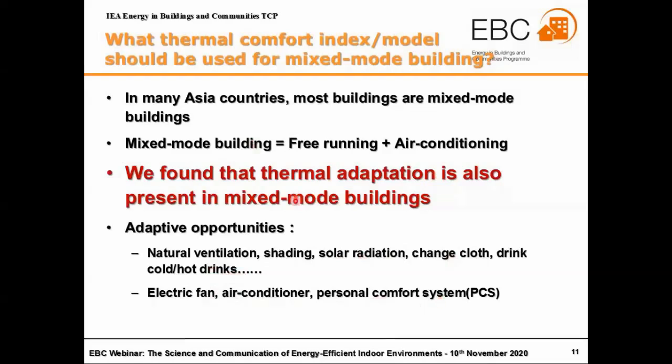In mixed mode buildings we used to use PMV, for air conditioning buildings, as a design criterion. But we found that the thermal adaptation phenomenon is also present in mixed mode buildings. So we think using PMV is not good for this kind of mixed mode building.